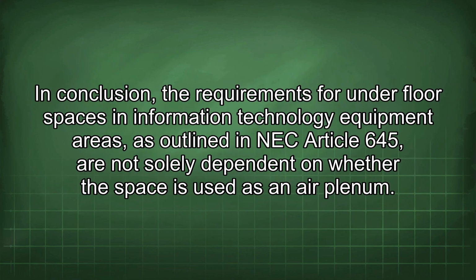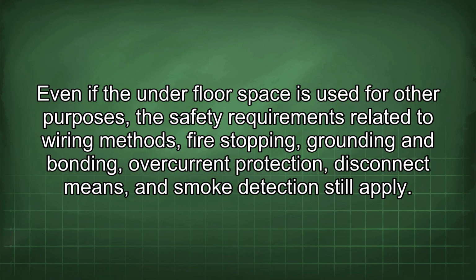In conclusion, the requirements for underfloor spaces in information technology equipment areas, as outlined in NEC Article 645, are not solely dependent on whether the space is used as a plenum. Even if the underfloor space is used for other purposes, the safety requirements related to wiring methods, fire stopping, grounding and bonding, overcurrent protection, disconnect means, and smoke detection still apply.